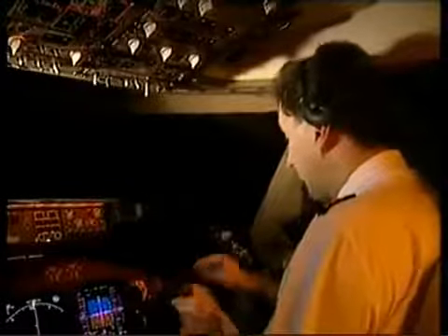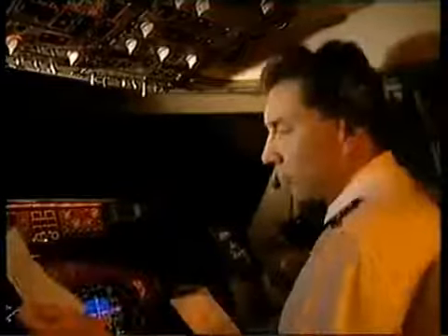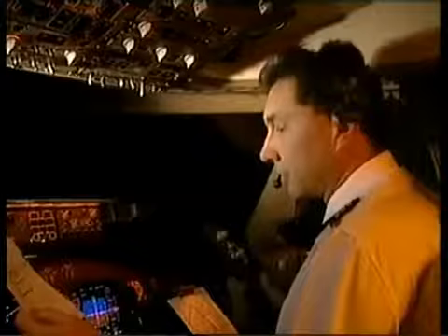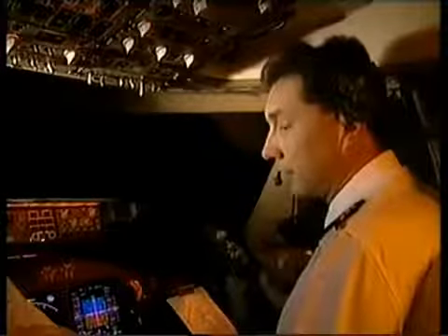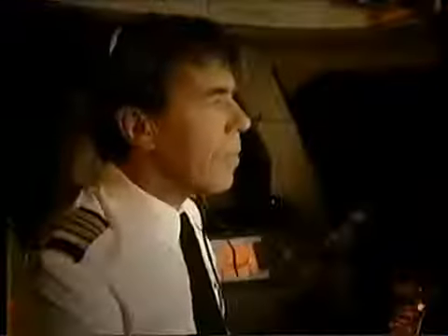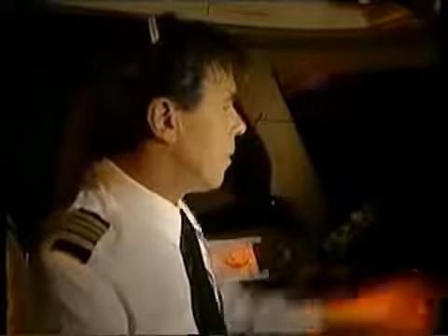Do we have the Sydney ATIS information? Yes, Captain. Sydney terminal information is Delta, runways 16 left and right, wind 180 degrees at 15 knots, QNH 1007, temperature 10, overcast at 300 feet, visibility 1,000 metres, showers in area. Independent parallel approaches in progress. Expect ILS PRM approach. Independent departures in progress. Thanks. Handing over and I'll brief the approach.